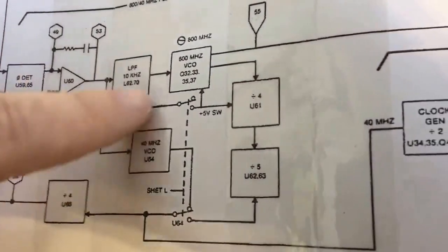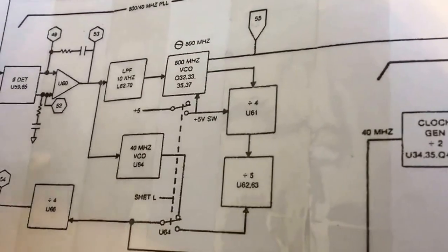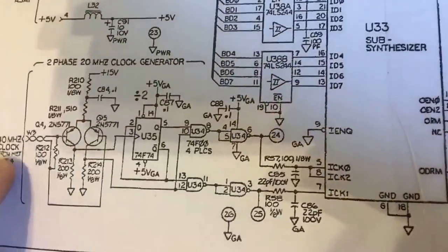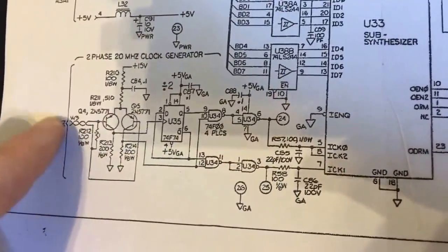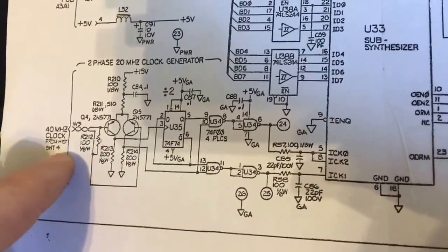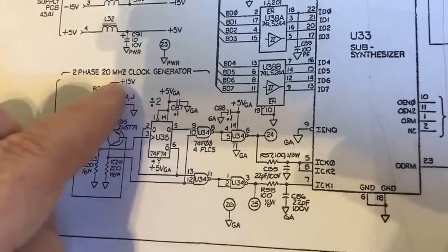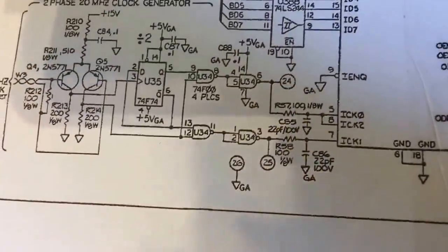So anyway, I know that this piece here is okay, because the frequency is okay, the scope looks good, so I'm confident that bit's okay there. So this section here I believe is okay. I've done some measurements here at this 40 MHz earlier on, because it's got a 20 MHz clock generator, and the fact it's out by 20 MHz was making me think, hey, is that a coincidence or not? Could there be a problem there? There still could be,